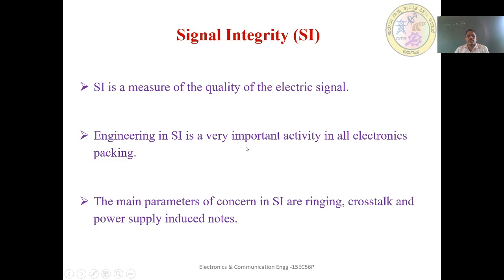Engineering in SI is a very important activity in all electronic packaging. Even while designing the connectors, the SI analysis has to be carried out. Whether the pins assigned to the connector are impedance matched or not is checked by using the signal integrity analysis. The main parameters of concern in SI are ringing, crosstalk and power supply induced noise.